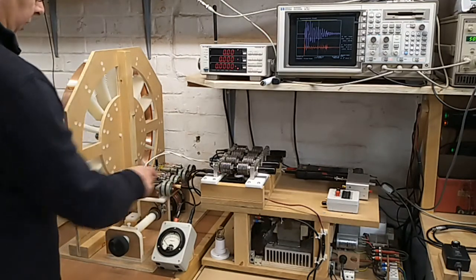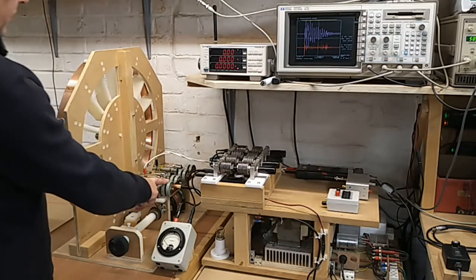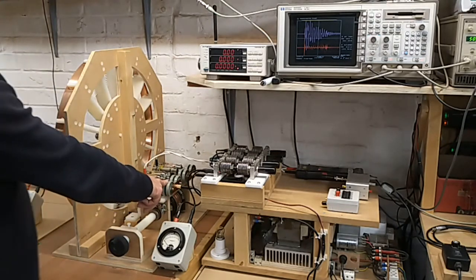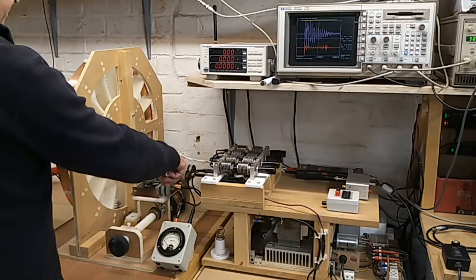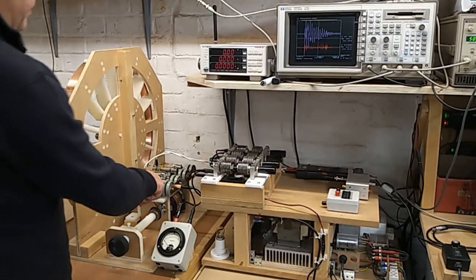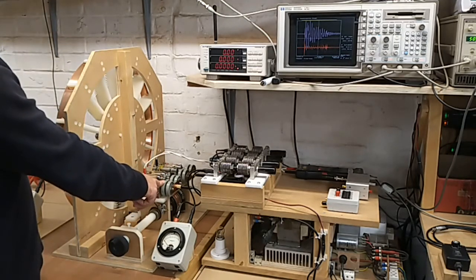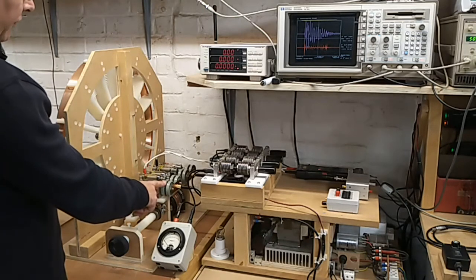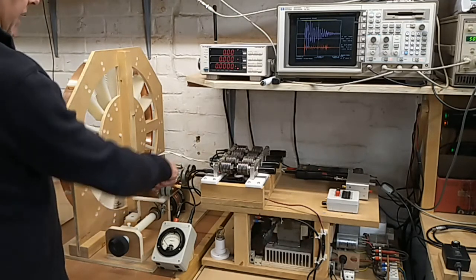That comes out, it goes into, this is the first half of the serial tank capacitor. So in other words, there are 4 capacitors here, doorknob capacitors. They are 4.7 nanofarads each, and we've got 2 in series and then 2 banks in parallel.